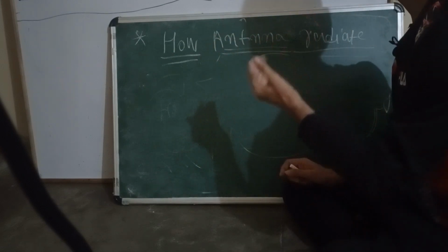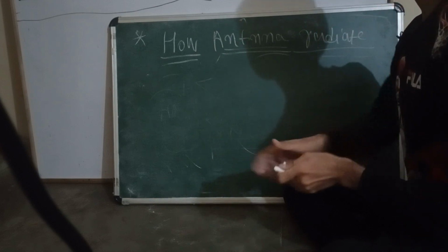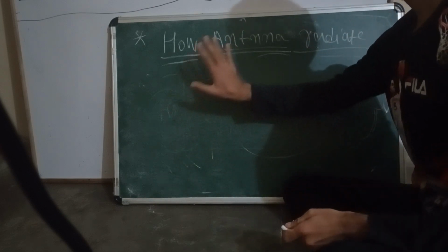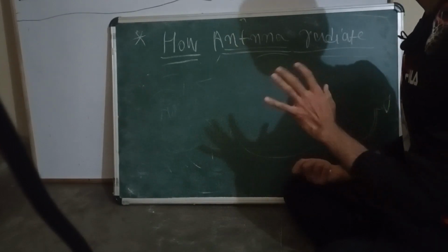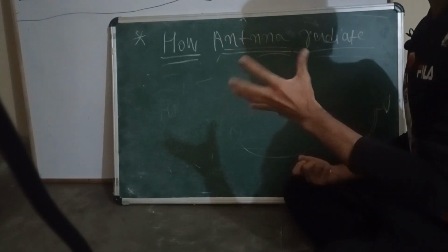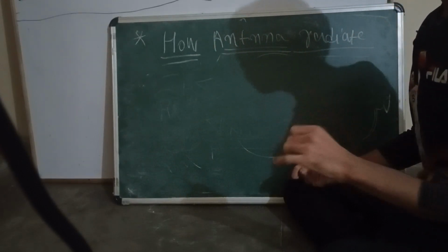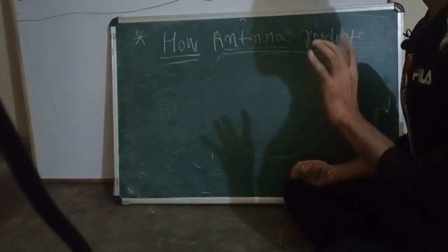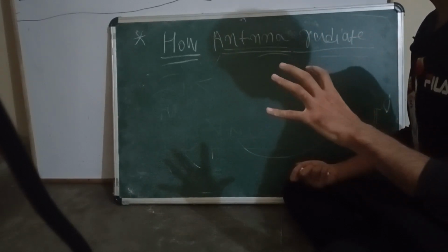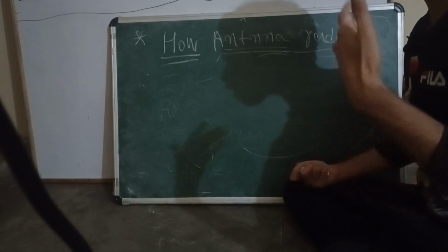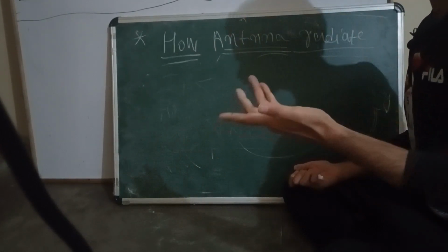That is why we have spent this much time on the behavior of charge. We are now confirmed that a change in electric field and magnetic field is what gets radiated from the antenna, which is possible only when the charge has oscillatory behavior, accelerating or decelerating, with its velocity changing with time.